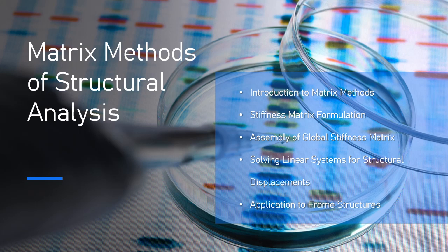3. Matrix methods of structural analysis. Application to frame structures. Frame structures, such as buildings, bridges, and industrial frames, consist of interconnected beams and columns that can carry both vertical and lateral loads. These structures typically experience both bending moments and axial forces, making them more complex to analyze than simple trusses or beams. The matrix methods of structural analysis are particularly useful for analyzing these structures, as they can handle large systems of equations involving many degrees of freedom and multiple types of loadings.